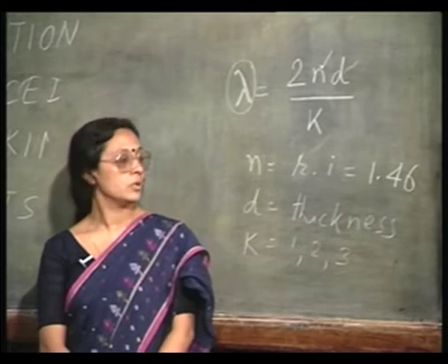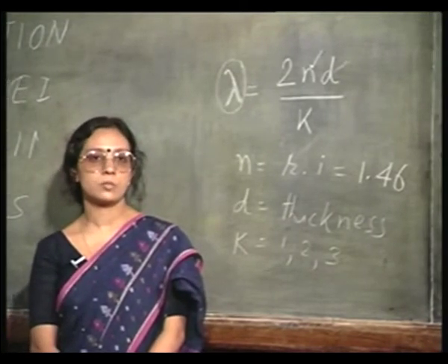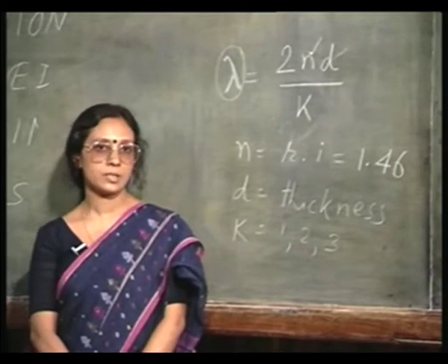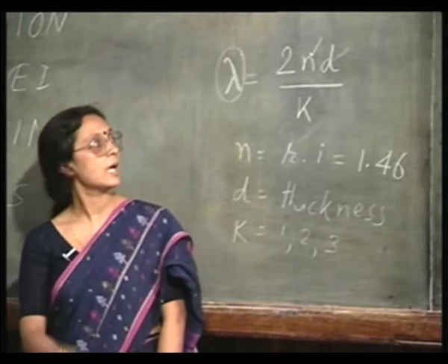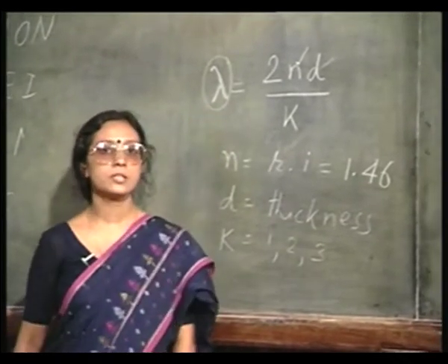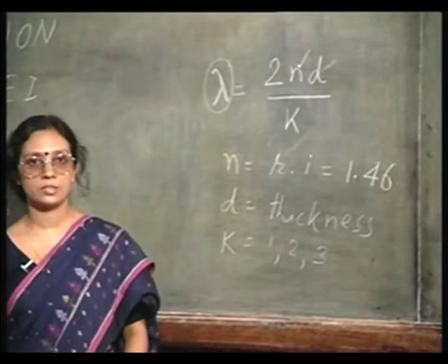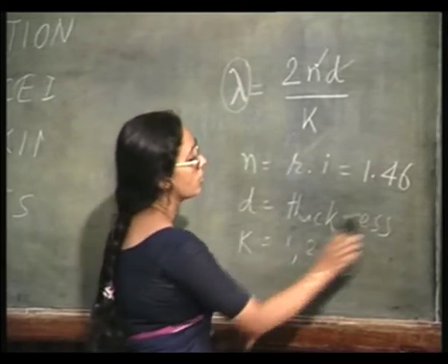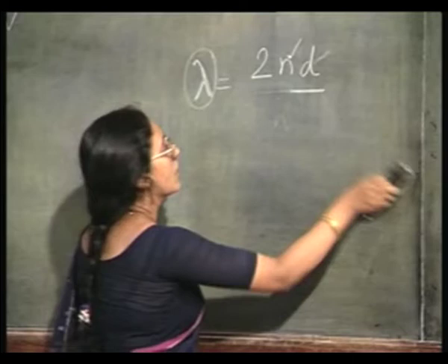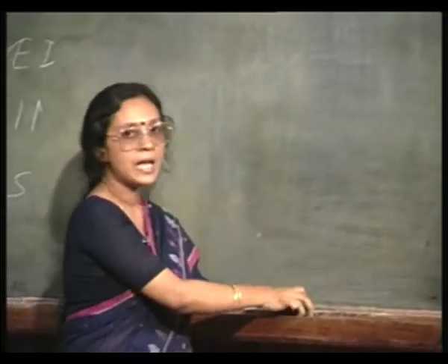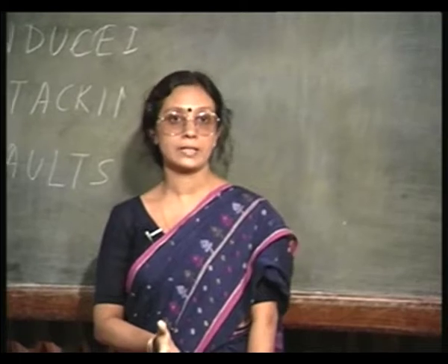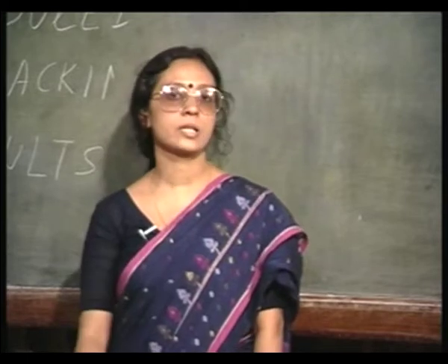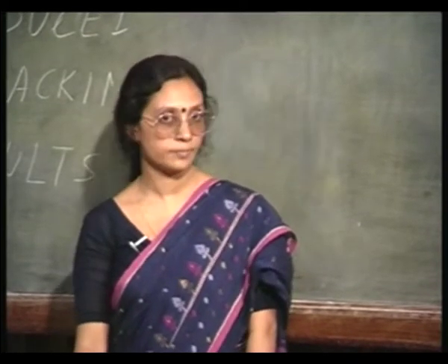Only one thing you need to know, that is, since you know the oxidation process time and temperature, you can estimate what is the expected oxide thickness, and then from there comparing with the color chart one can find out what the actual thickness is going to be. Of course, there are other much more accurate methods of determining the oxide thickness, but this is nevertheless a very handy way of doing that. Simply by looking at the color and comparing it with the color chart, one can say whether the oxide thickness is 600 angstrom or 800 angstrom, things like that.